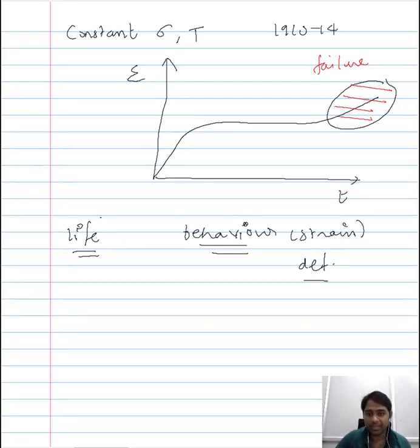Now, when we talk about the life of a material at high temperature, as we discussed earlier, the life of a material in a particular application largely comprises the steady state condition here. This is just a schematic curve, and even here you could see the curve largely comprises the steady state region. In the similar way, when you have a material being used in an application, the material spends a substantial part of its life in the steady state condition. And that is the reason why, when we talk about a given creep mechanism for a definite stress and temperature, the expression that we get for a definite creep mechanism is expressed as the creep rate at steady state condition.